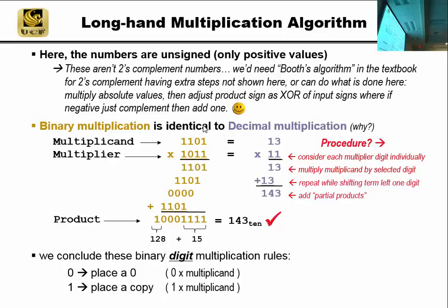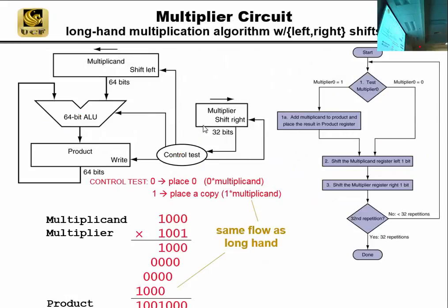So what we're doing is adding each of these partial products, but we keep shifting the multiplicand's weight left by 1. That's going over here. Every iteration through, we're going to increase the weight, which is a power of 2, same as a power of 10 when you did it in decimal in grade school, by shifting 1 digit to the left. Every iteration through here is 1 digit. A bit is a binary digit.